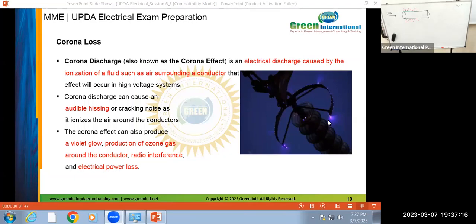Then the same hissing sound is referred to in the induction motor also. In the squirrel cage induction motor, we use a skewed rotor, which is used to avoid magnetic locking and the hissing sound. And for voltage regulation, the leading current effect, we call it negative voltage regulation. At the same time, in the induction motor we have a negative slip. When we have a negative slip, the induction motor rotates above the synchronous speed.